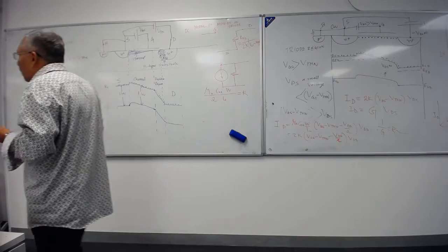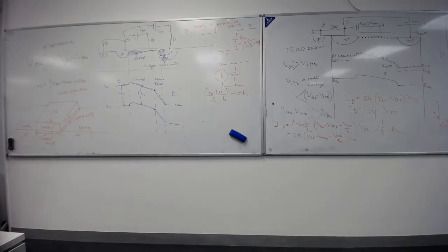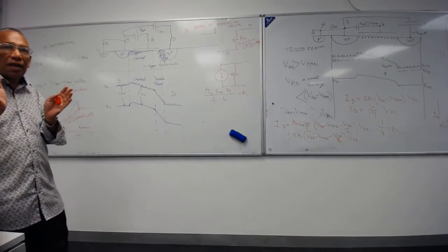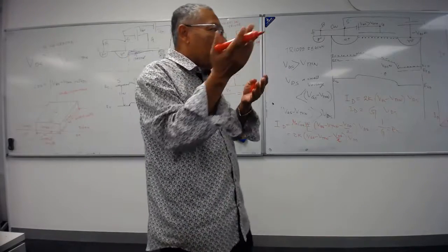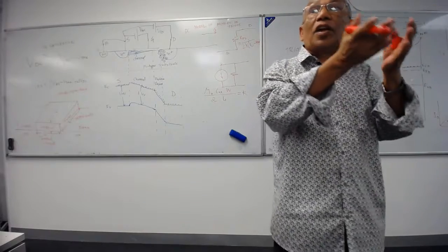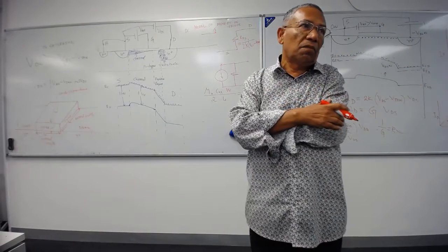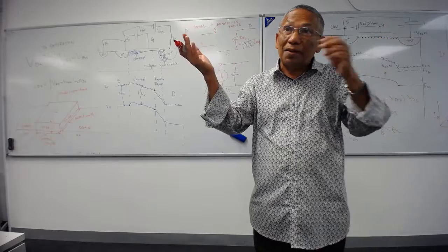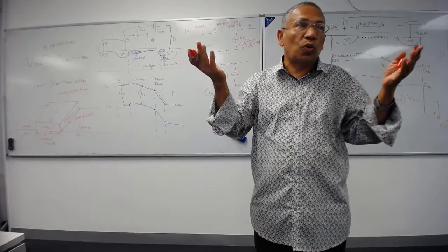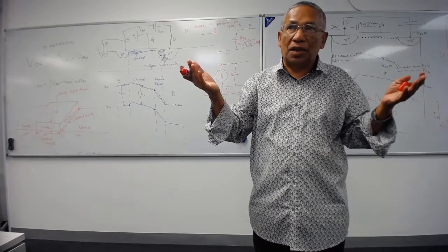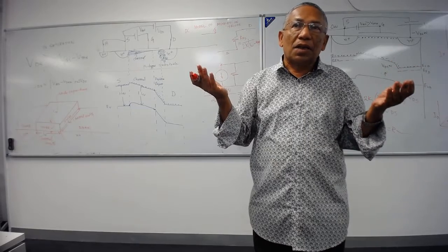We can just find the IC set, divide by 10, get a base current, and use that base current to determine the base resistance. Everybody remember that? That's the way we do it. So you know how to do that part, BJT. What is the IC set? This is the IC set.